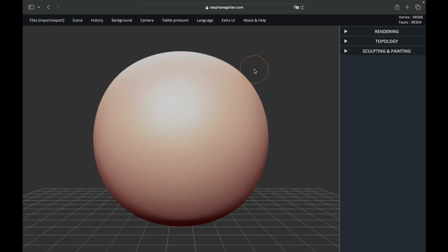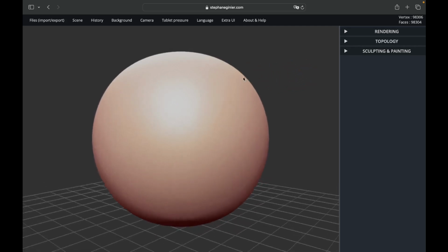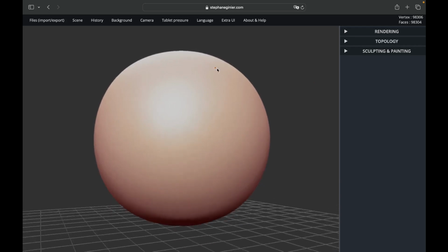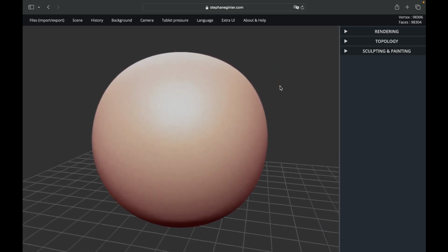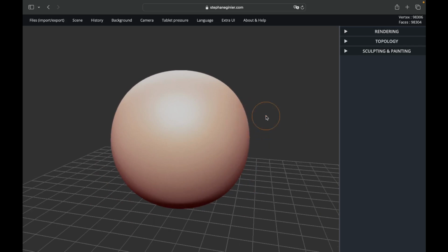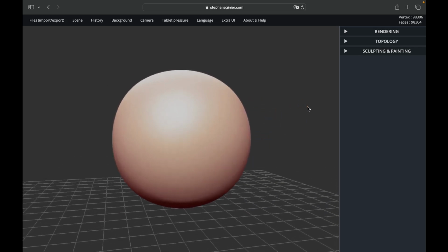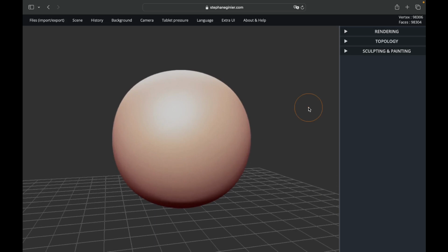As in other cases, by opening the program, we will find a default sphere within our workspace. Our modeling will start from a sphere, so we can work on those provided by the program at the start. First, let's establish the number of actions we can restore during work. I recommend selecting the maximum number of actions provided by the program, especially for those who are new to using this program. So let's go to history and slide the max stack slider to the right. By changing this setting, we can proceed with modeling.